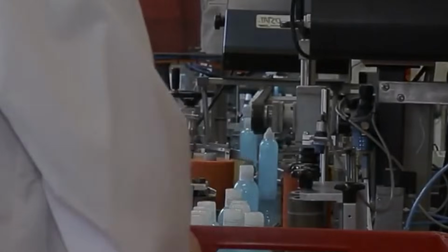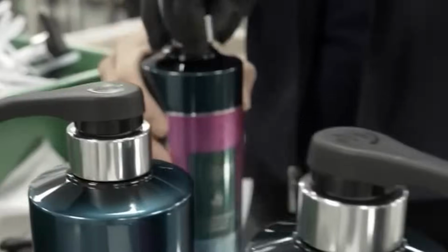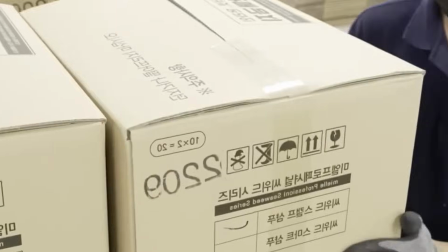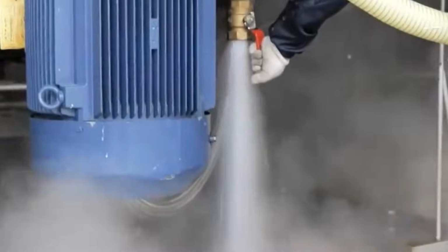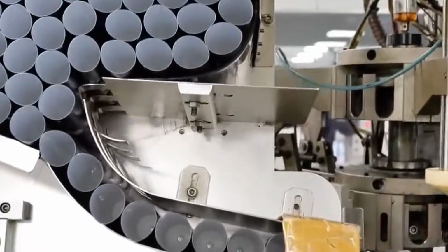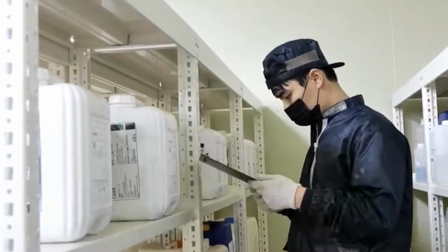Once all ingredients are added, the batch undergoes a final homogenization phase. The shampoo is circulated through an inline rotastator mixer or colloid mill to eliminate microlumps, improve clarity, and ensure uniform viscosity. Shear rates are carefully controlled to avoid degrading polymer thickeners or breaking silicone emulsions. During homogenization, air entrainment is minimized. Some systems apply vacuum to the mixing vessel to remove entrapped air bubbles. Vacuum levels are controlled to prevent excessive evaporation of volatile components such as fragrance.